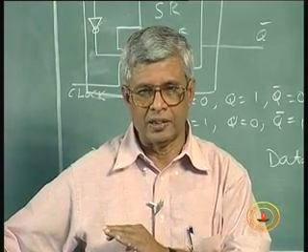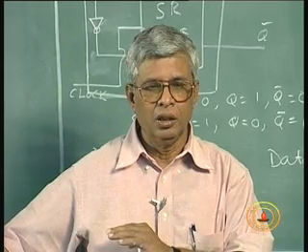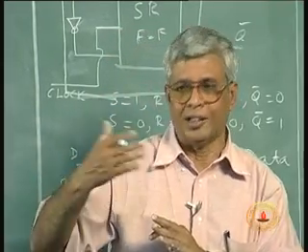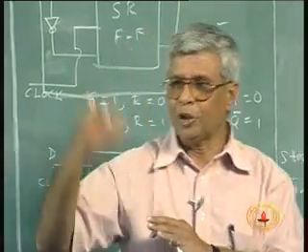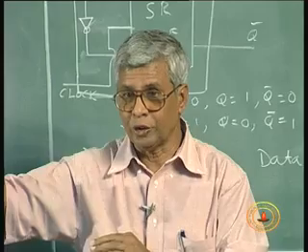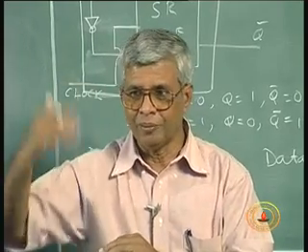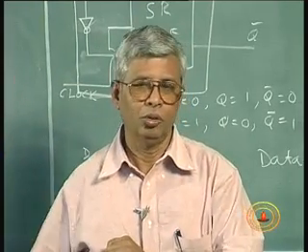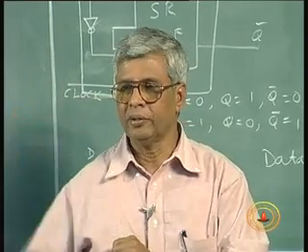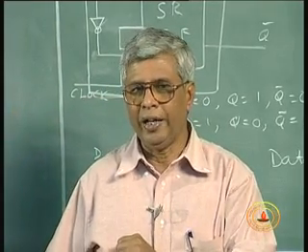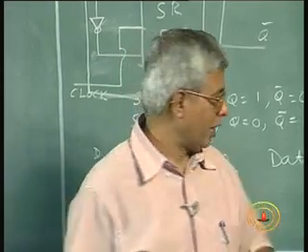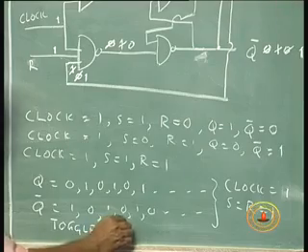In the SR case, yesterday we analyzed that. Whereas now we can say that it is predictable but useless. Output keeps changing from 0 to 1, 0 to 1, 0 to 1, all the time. But it may be useful sometimes. This constant changing is called a toggling operation. In fact, it changes so uncontrollably that they call it racing.